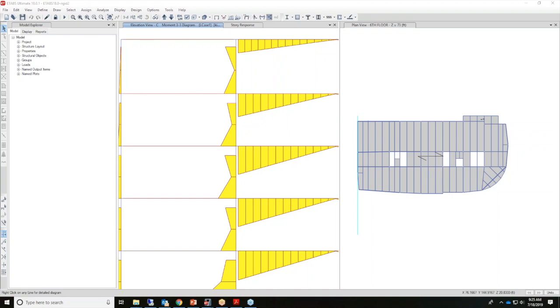Okay, how is response spectrum analysis applied only above grade? During response spectrum analysis, the loading is applied to the entire structure, though subgrade modes will have higher frequencies, but they will be providing minimal contribution to the modal response. However, mass participation of subgrade levels could be subtracted from the total mass.